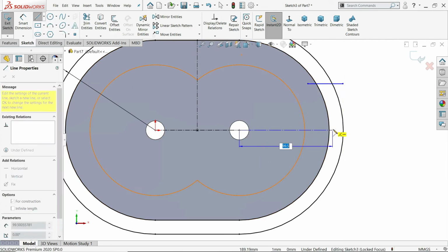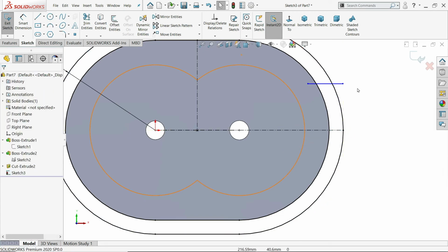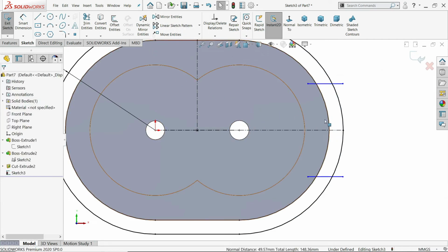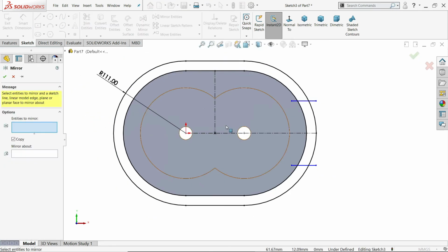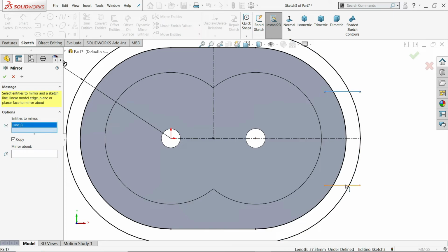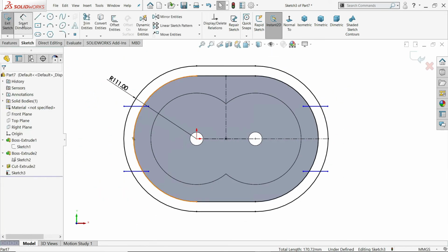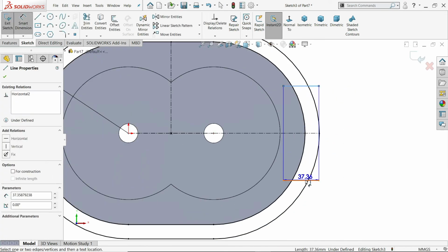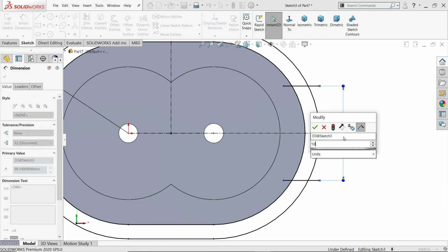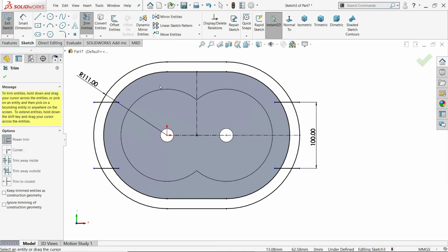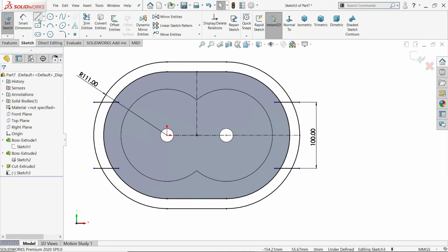Okay, let's create a line. Now select, okay, there is too many things, so mirror entity, see here, make sure this is vertical. I'll choose these two lines, mirror about this section, say yes. Let's define the distance, 100 millimeter. Trim entities, okay, let's define trim later.